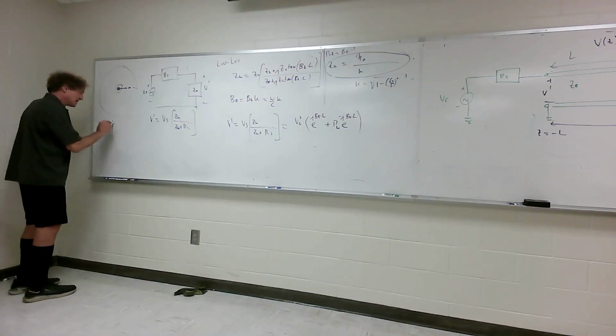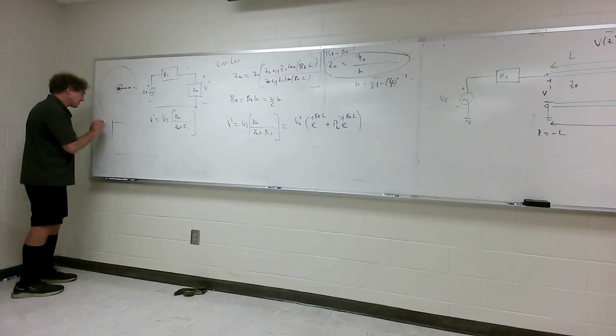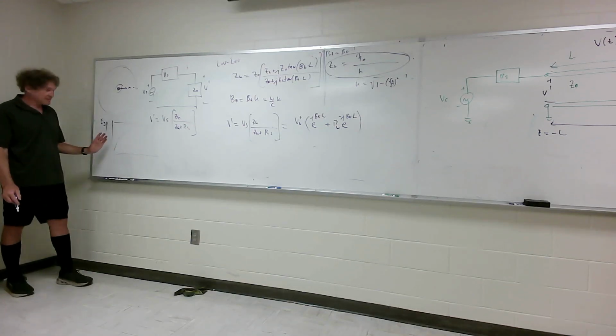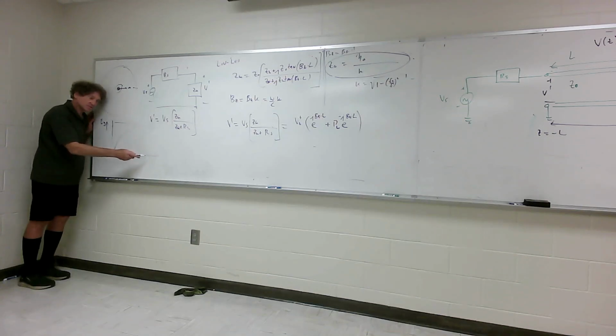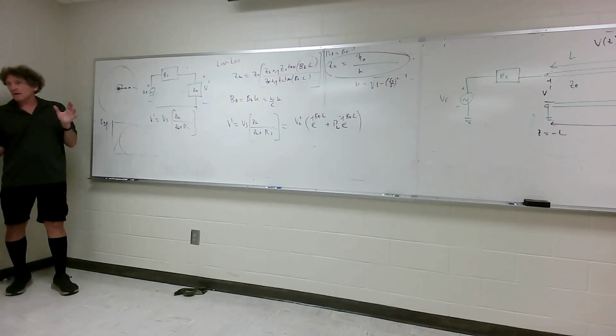So with a waveguide, it's rectangular. And if you plotted the field, say we're in the TE10 mode, so the electric field in the y direction would look like this. Now that field will have no variation in the vertical direction. It'll be the same electric field magnitude from right here to right here. It'll have the sinusoidal variation. When you integrate the power density, if you just take a look at the power flow, 1/2 E cross H, take a look at that.